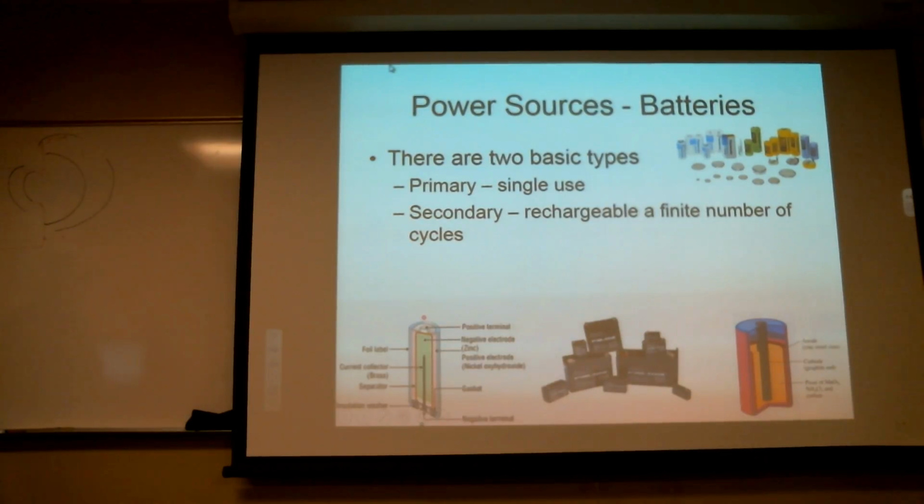Which direction is the current going through on those batteries? It's coming out of the negative and going to the positive for discharge. Now, if it's a secondary cell where I can charge it, when I'm charging it, it's going to go the other way. We're going to pull them out of the positive and shove them back into the negative, just like filling the tank.